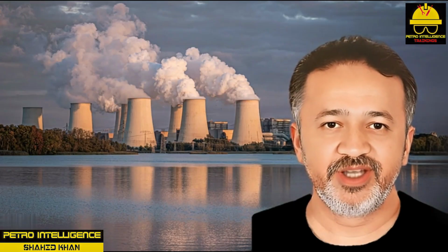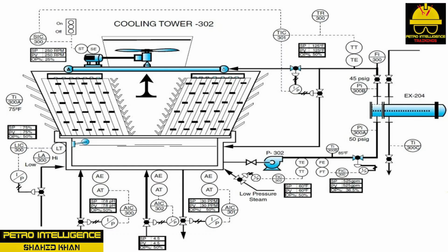Suspended Solid Chemical Control, AIC 302 Analytical Indicating Controller. The purpose of this controller is to control scale, algae, corrosion, wood decay, and to help suspended solids to precipitate out in the basin. AIC 302 monitors conditions in the basin and maintains unit specifications by adding liquid chemical treatment. Liquid treatment is set at 4.5.